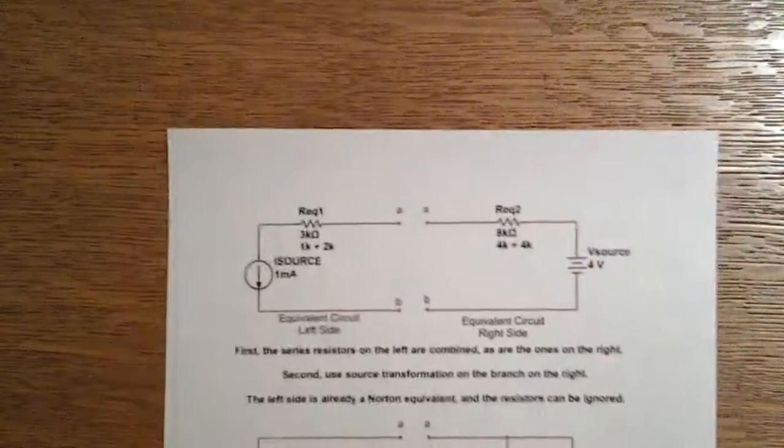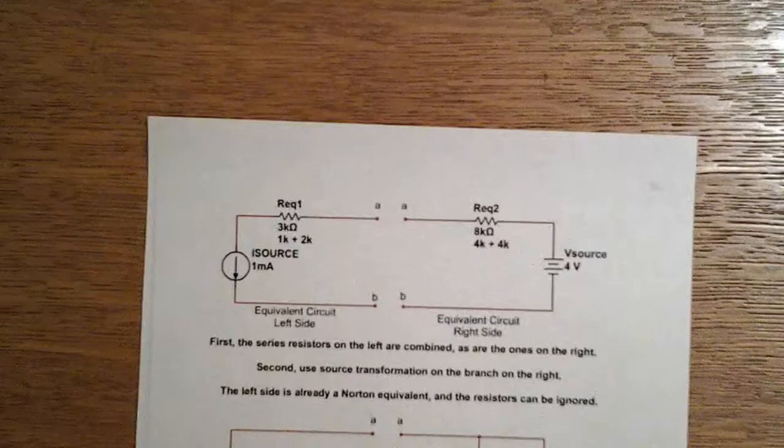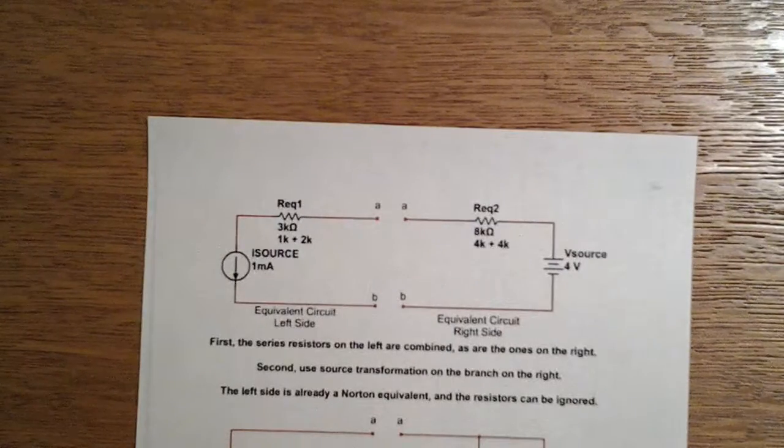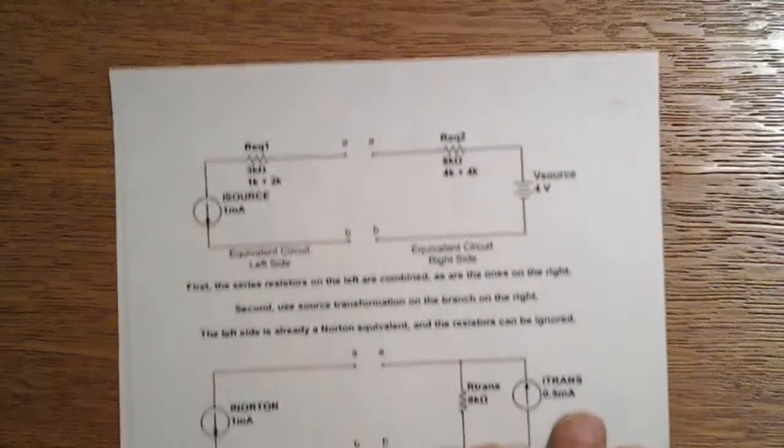Now, we'll separate this circuit at A and B and make two circuits. We chose to work with current sources as this was easier. The right half is a voltage source and already configured as a Thevenin circuit. So we will convert it into the Norton equivalent.